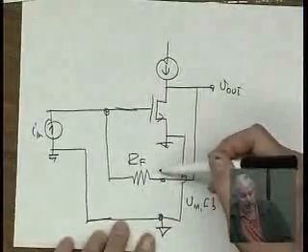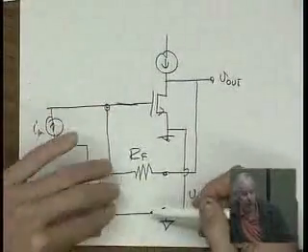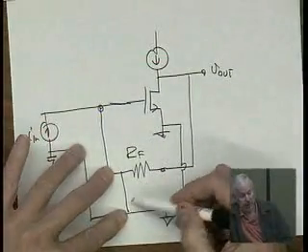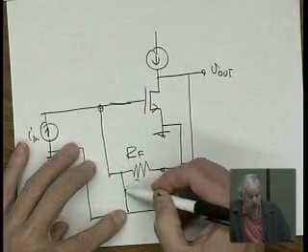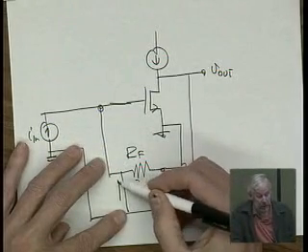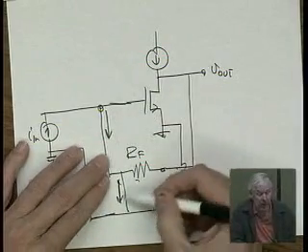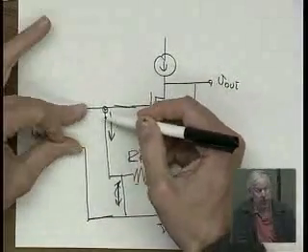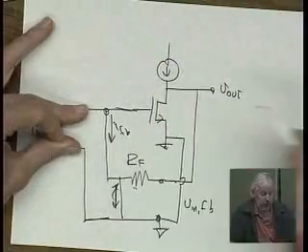So you see that? Now we need to calculate what this feedback factor is. How do we do it? We take this output and short it. We apply a voltage here, and we see how much current goes into this feedback network. Feedback factors like this, so we have to figure out how much comes out of this feedback network. So we short it. I could short it up here if you want to look at it that way, and calculate what that feedback current is.